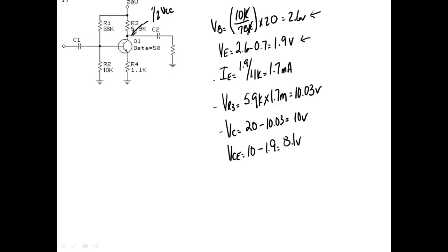Okay. What are we looking for on this? And this is going to be on the test, by the way. If it's less than 1, we say it's what? Saturated. If it's equal to VCC, it's cut off, right? And if it's between, then it's active. Okay, so what do we need to do now? Need to calculate voltage gain.